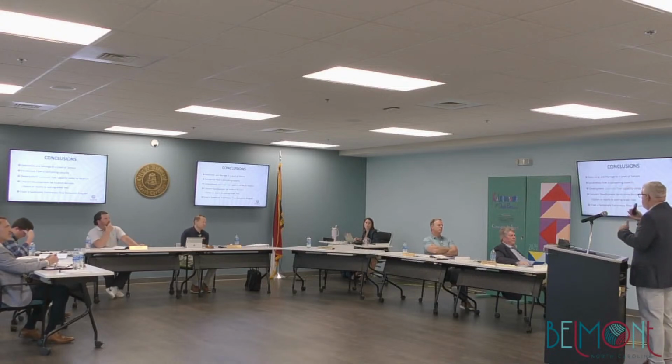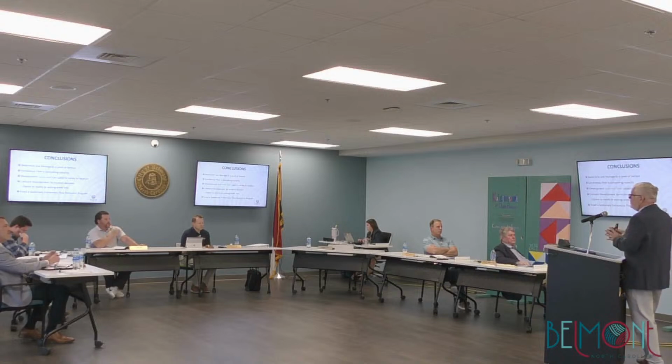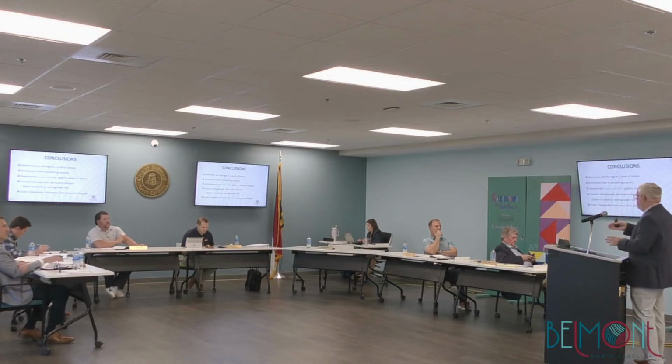But yeah, the key here on that last one is systematic. This is something that needs to become part of your regular operation and maintenance. Smoke testing, CCTV, continue to find this. This is not something where you're going to go out next week and find a big hole in the system, fix it, and all the problems are solved. This is just going to be chipping away at it, year over year, removing that out.